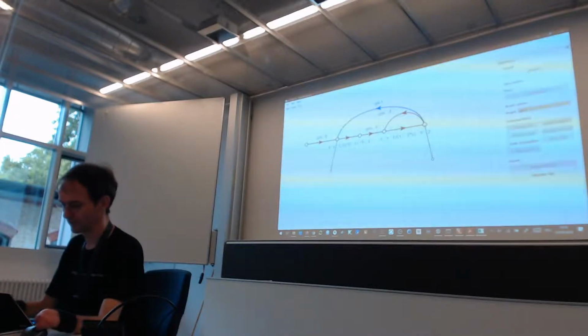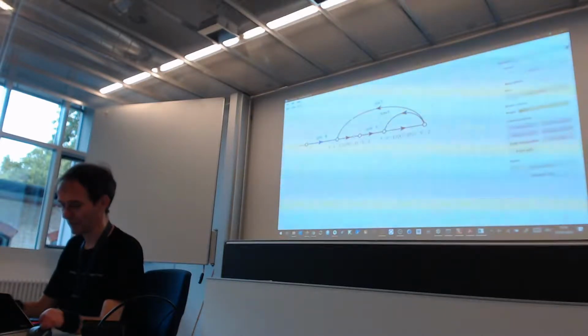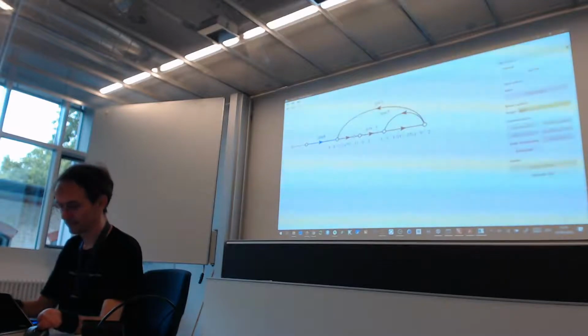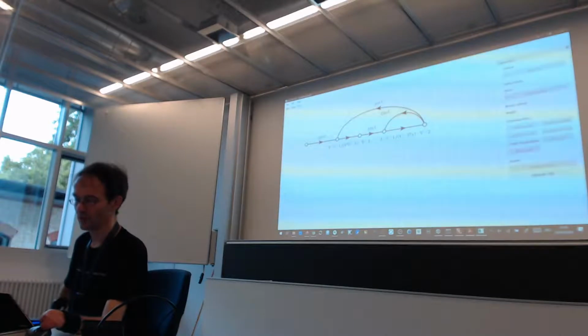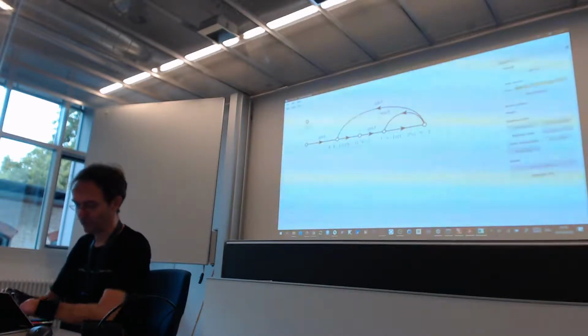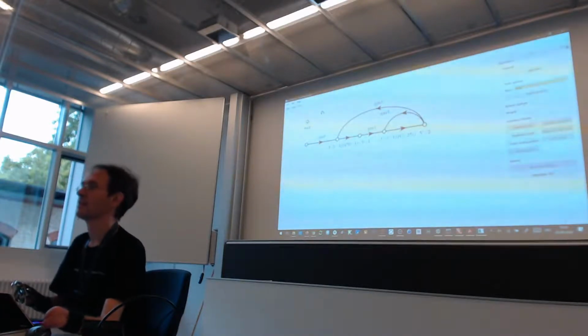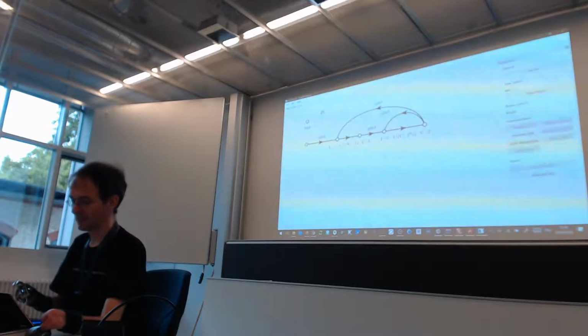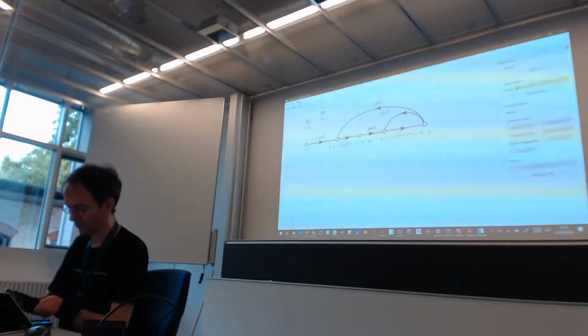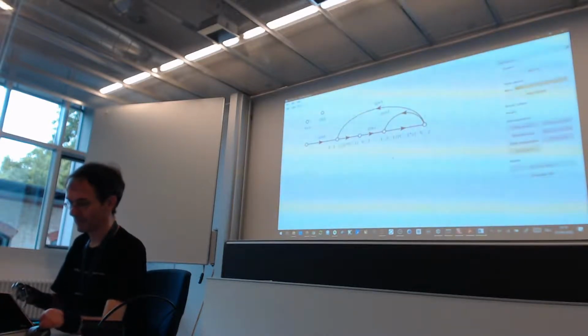Let's make it a little bit more compact. And now all of those here should have input noise sources. So the GM4 would have a VN4, the voltage noise source of GM4. Then the GM1 would have a VN1, and this is another GM1.